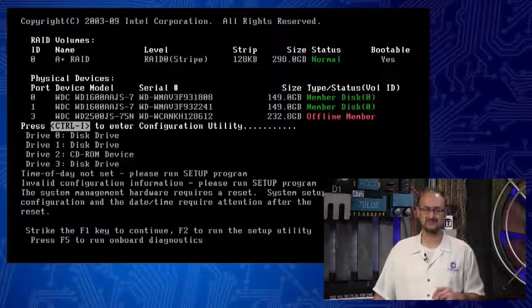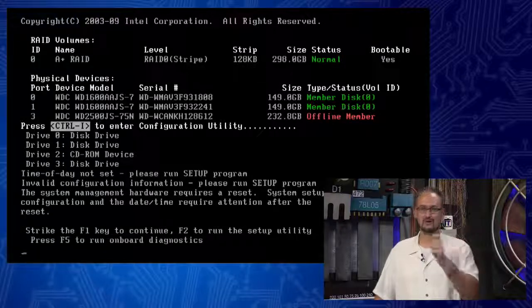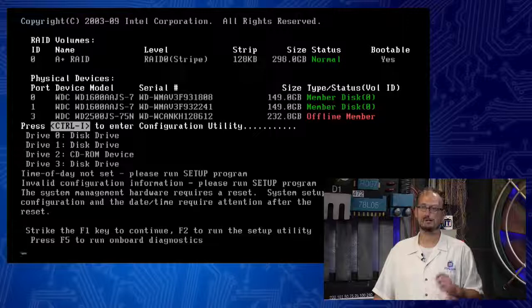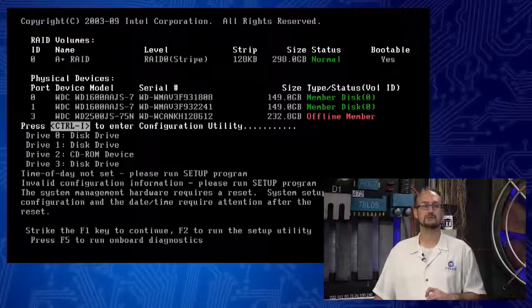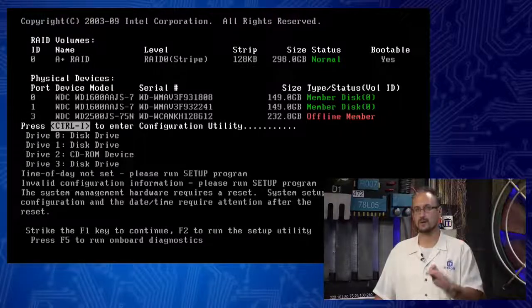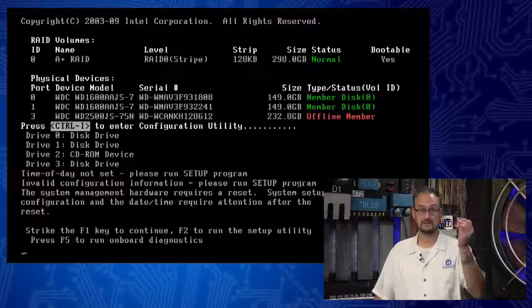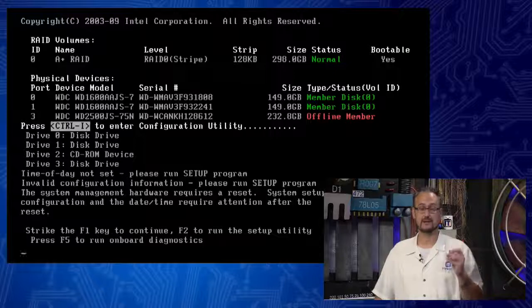It's holding all of these configurations. And now that we don't have power to those configurations, volatile memory, right? Even if it's low voltage, if it's volatile memory, no voltage means no configuration. So this is what you can see if the BIOS settings are reset, like they say, the BIOS time and settings keep resetting. Well, it basically means this is the problem. This is the little battery.